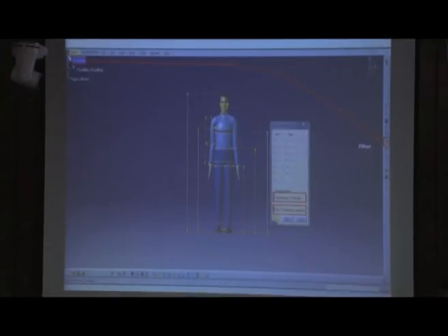In that window, you first select this one called filter. In that filter, various parts are there that you can go for: part, body, head, torso, arm, hand. In this, various body parts are there. Types, what type of anthropometric variables you want to consider, like circumference, height, length, breadth, depth, mass. So all this is possible. Now here we can go for manual. If you want to manipulate it, we can put it manual. Then we can go either one or individually, or we can select all at a time. So while you are putting all, then all the body parts and all types of anthropometric variables will be displayed on the human body, and each of the body segments and its anthropometric dimension we can modify.